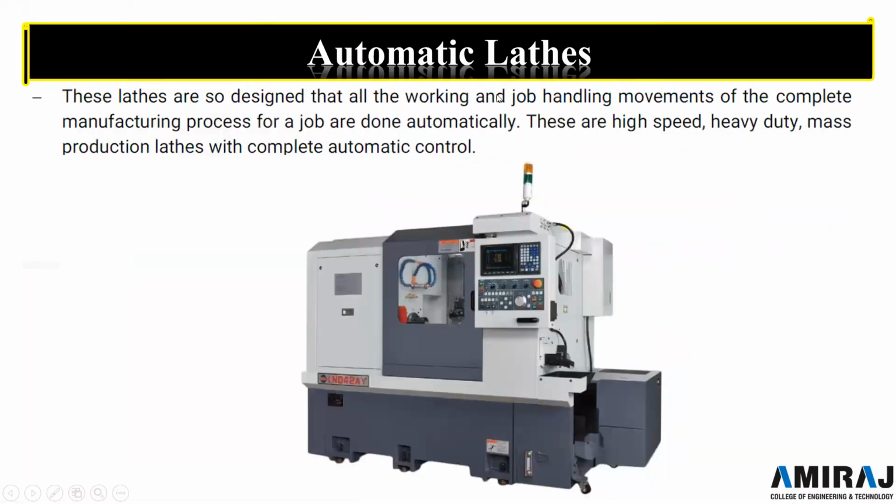Another is automatic lathes. These lathes are so designed that all the working and job handling movement of all the complete manufacturing for a job is done automatically. These are high speed, heavy duty, and mass production lathe with complete automatic control. They are having the complete automatic, just we have to fix the workpiece and after entering the code, okay, G code and M codes in the CNC machine, the complete operation takes place in the automatic form.